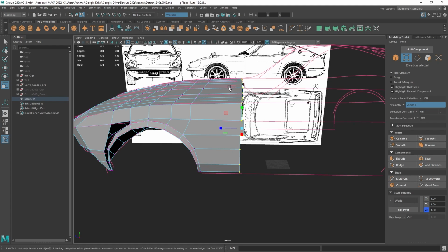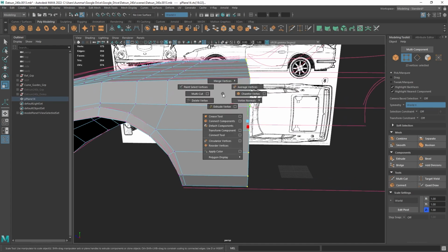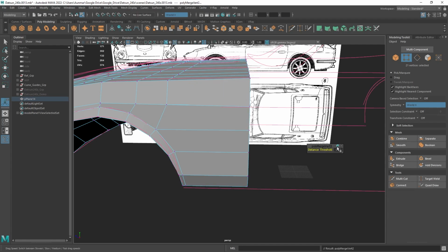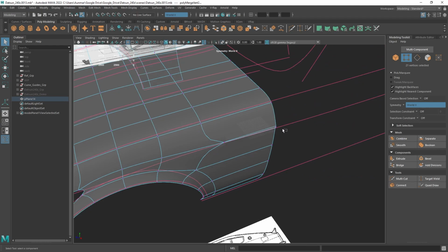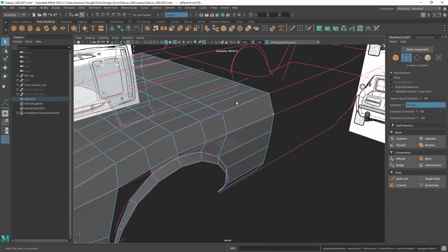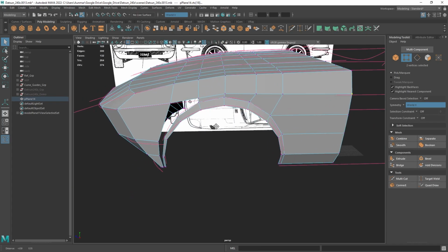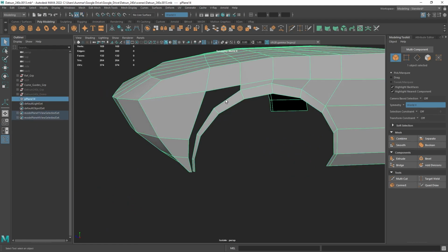We just basically select them all, scale them in one axis to get them all aligned, and then do a simple merge vertices at a low threshold. And there you go. And then they're all attached except for that one. So I can just do a quick merge to center, and there you go. And I'm just, again, toggling between 1 and 3 to make sure how things are looking, and that'll be completely fine. So selecting the front fascia again.